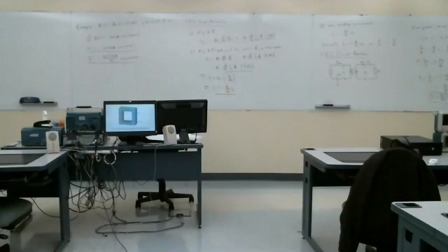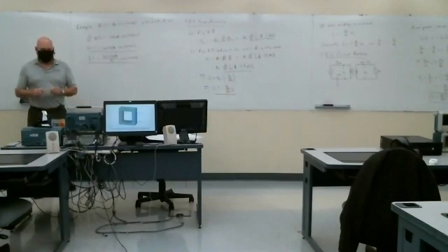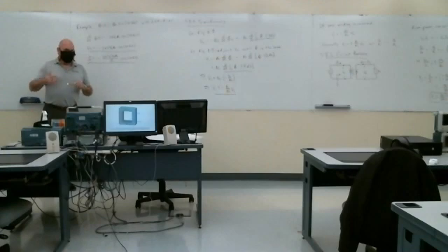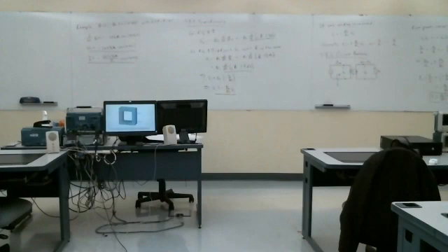The other thing, terminology you remember from circuits, is we talk about step up and step down transformers. That refers to voltages. So if N2 is greater than N1, this ratio is greater than 1, which means V2 has got to be greater than V1. So that's a step up transformer. That means the secondary current has to be smaller than the primary current, though.